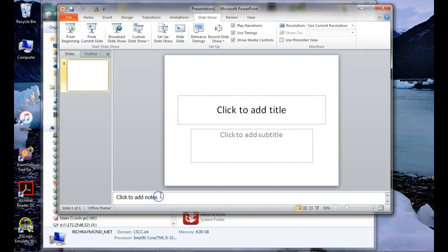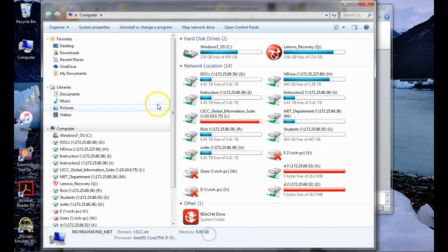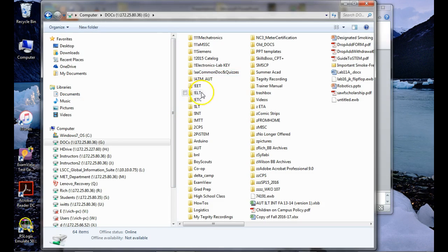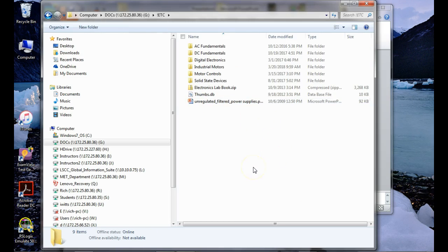Review. It says, falling down data sheet term. Yeah, you've got VRRM. That's what the data sheet calls it. Unfortunately, books, and we talked about this in class, books call it peak inverse voltage, which is the breakover voltage. Data sheets call it VRRM, repetitive maximum. So if we look at the data sheet and you're looking for PIV, you're not going to find it.